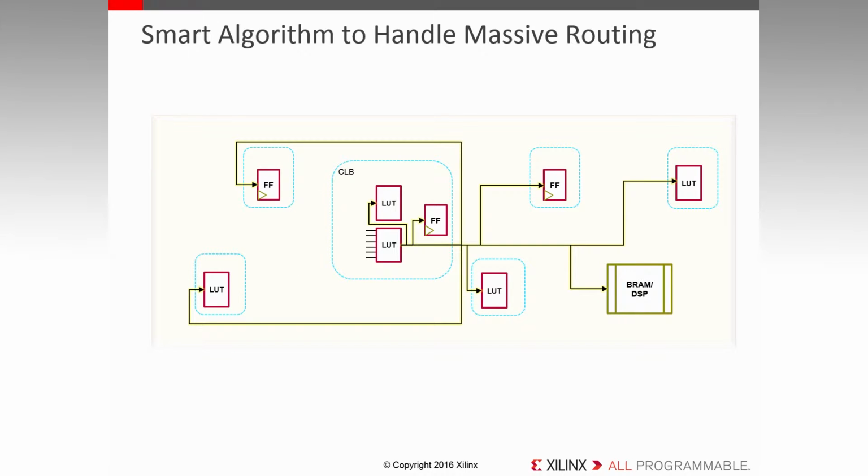However, UltraScale fast-track routing and optimal packing use efficient routing techniques with variable wire lengths. The fanouts within a CLB use logic routing, which doesn't contribute to external signal power, whereas the fanouts in different clock regions will have different wire lengths. And also, the node capacitance at every horizontal or vertical interconnect track varies depending upon the choice of routing path.